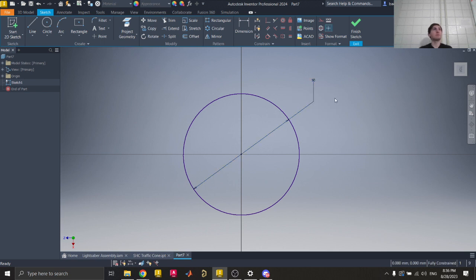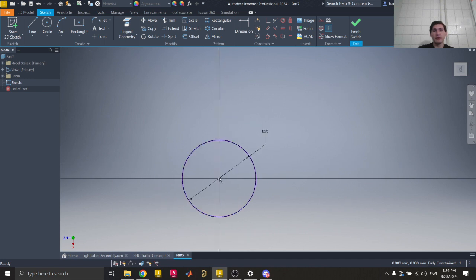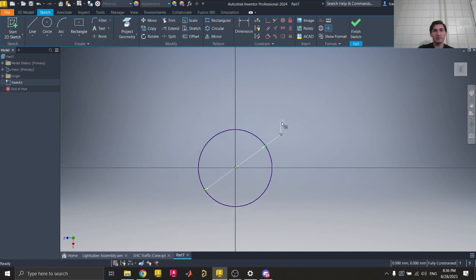If you want to cross into the dark side and use different types of units on the same part, it is possible to do that. The way that you can do that, you have some number, and if you want to use something other than whatever the default units for your file are, you can get rid of the unit extension, and let's say I want it to be 50 inches. I can do that. It's going to be big,